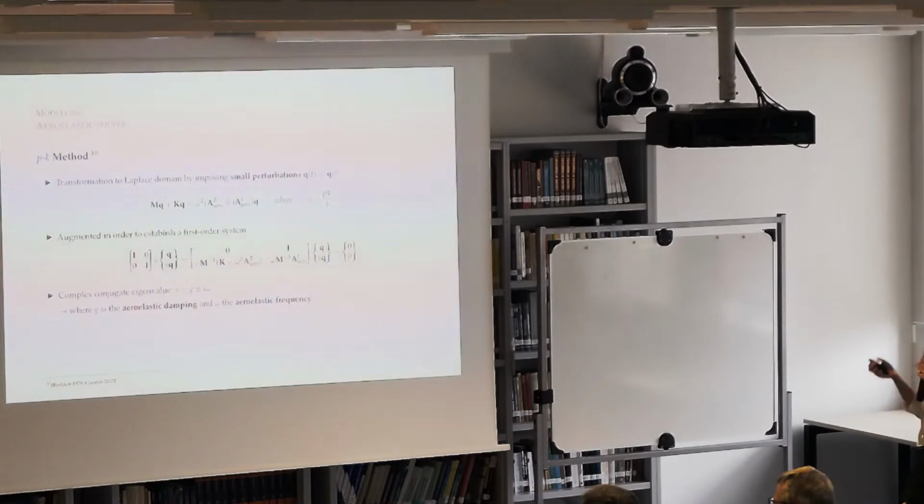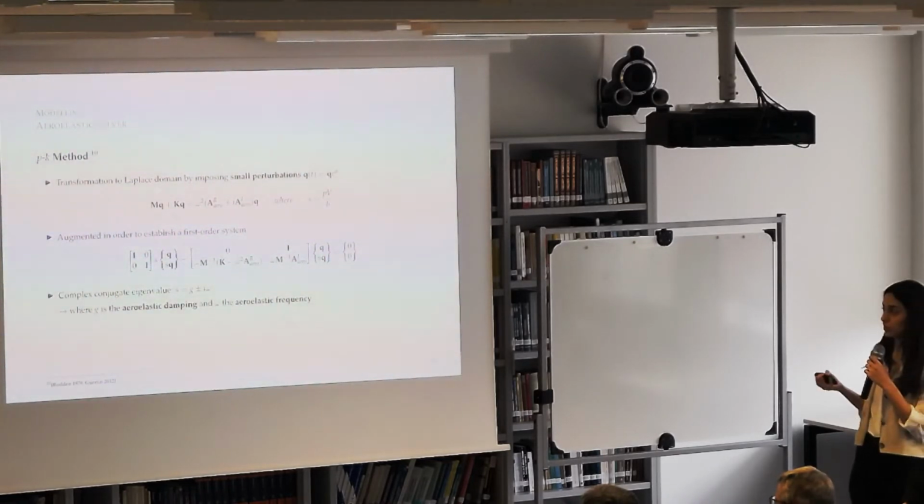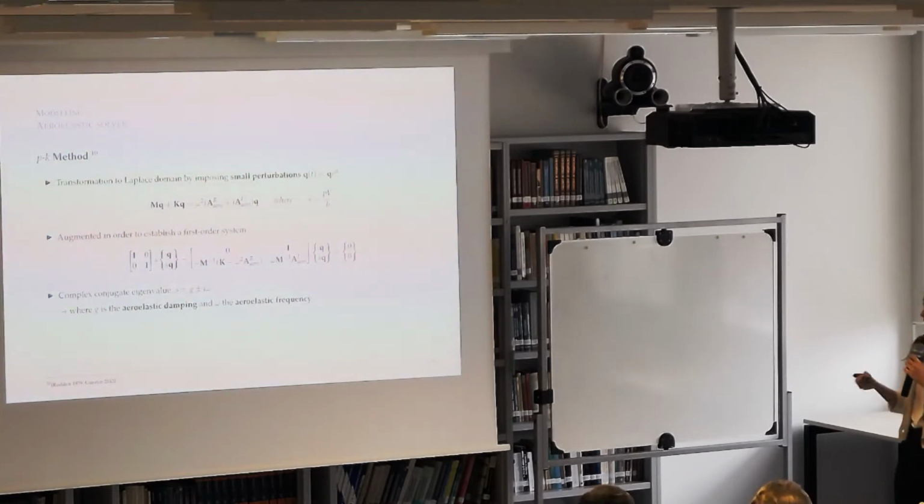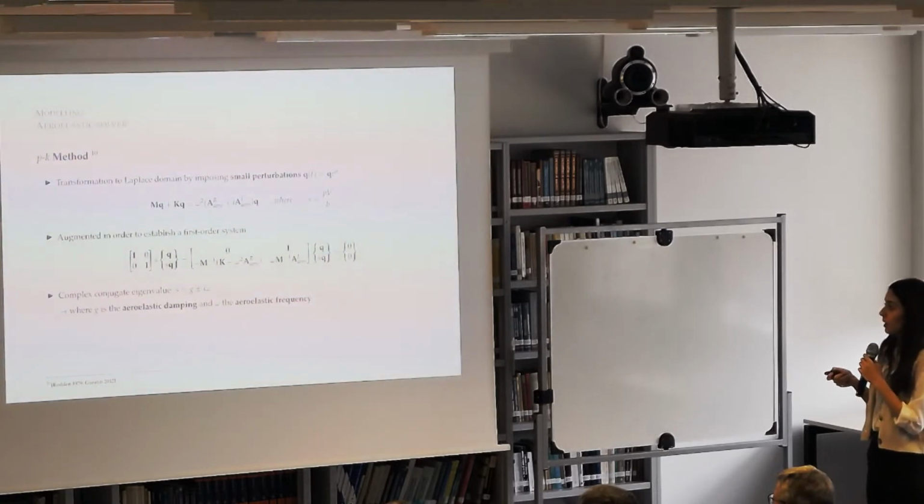Once I have my aeroelastic system, I need to solve it in order to predict my instabilities. In order to do that, I use the PK method, which is a very common aeroelastic solver, very easy to code. What it does is that it transforms my equation in the Laplace domain by imposing small perturbations. Here I have